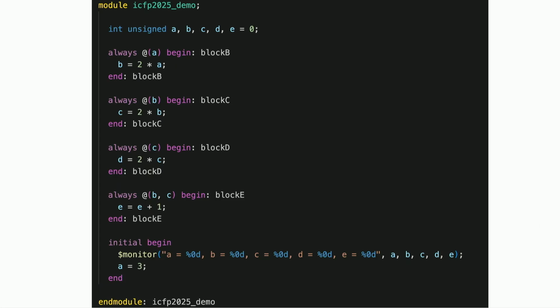So let me just give you a bit of insight into the underlying semantics of these languages, VHDL and SystemVerilog. Like I said, they're based on these concurrent blocks that are waiting to run. Each of these blocks is typically blocked waiting to read in some signal. When the value in some wire changes and they're listening to it, they run the code in that block. And that code is run sequentially to the end, and it can have state, it has a program counter, right?